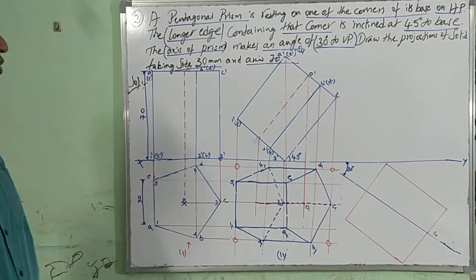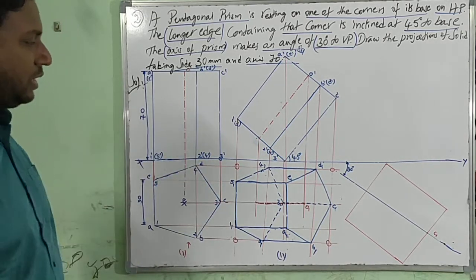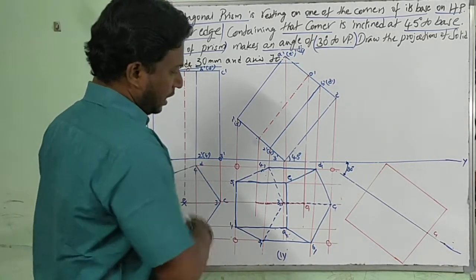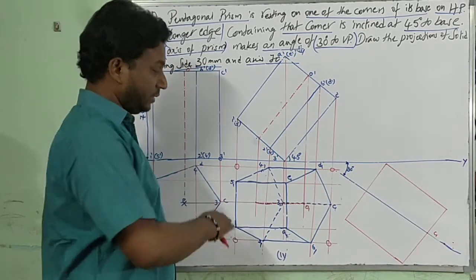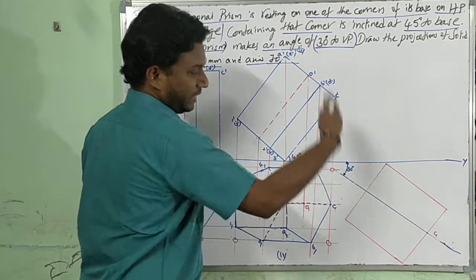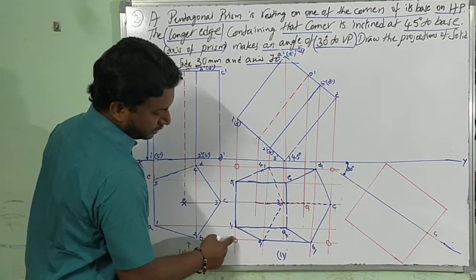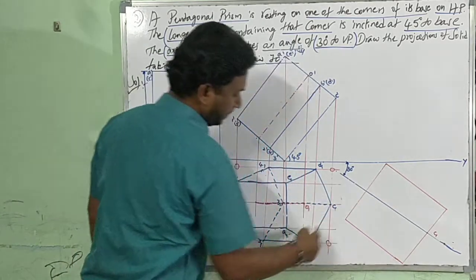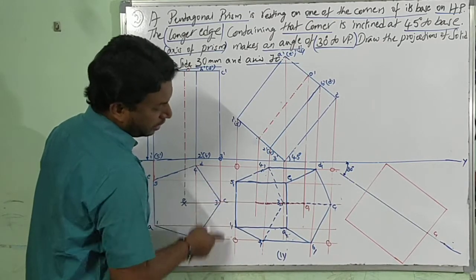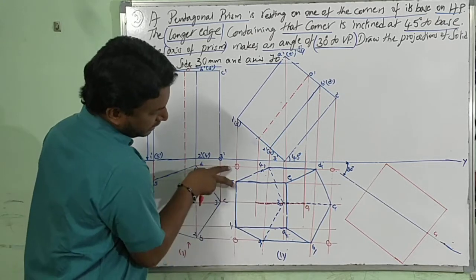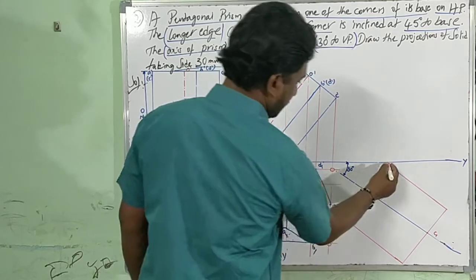With respect to the center line and 4 circles, I have reconstructed the box. Now in that box, I have to draw something like a graph sheet, right? A graph sheet is nothing but horizontal lines and vertical lines. See, now you can observe this here, here. Now from here, 1, 2, 3. 3 horizontal lines are supposed to be drawn. Measure the distances. 1, 2, like this. So from that I can easily locate.